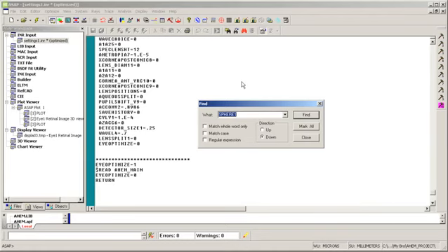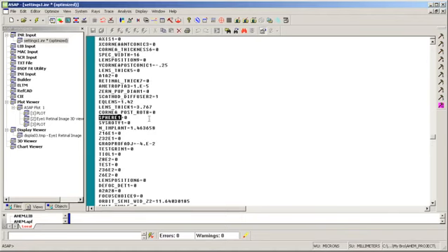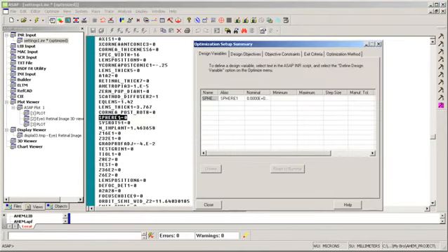And all these variables are listed within AHEM's library. So I'm going to find sphere 1. There it is. So I'm going to select it, and I'm going to right click on there, and I'm saying define design variable. So its original number is 0, and now the optimization is going to figure out what the best power to put on the correction lens will be.